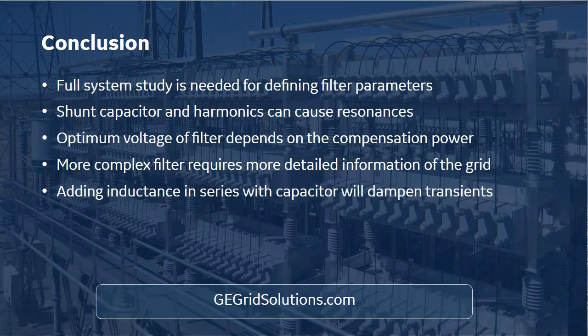Again, with medium voltage it might not be the case, because you can get a little bit cheaper by playing a little with the bank connection. For example, you can connect 2 caps in series per phase, or 3, and change the number of parallel units and so on. But if you have a high voltage capacitor bank, the cheapest bank will always be when you have the highest kVAr rating possible and the highest voltage.